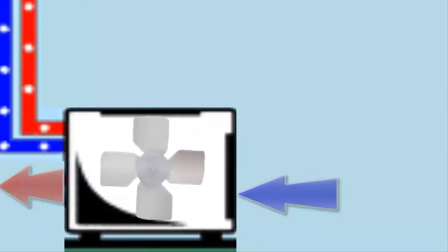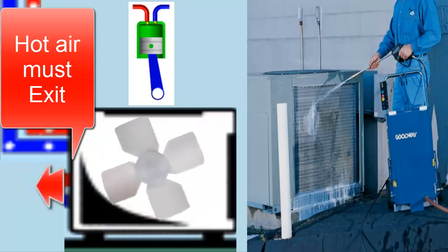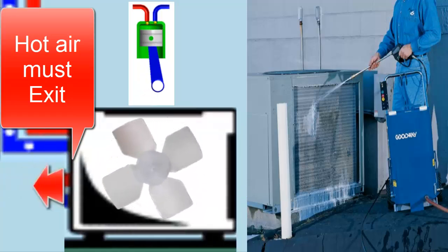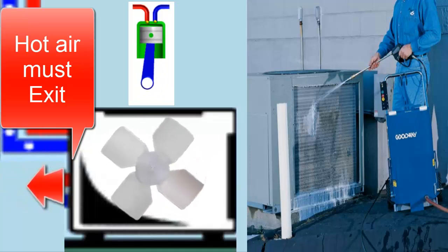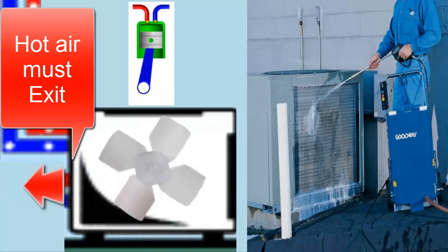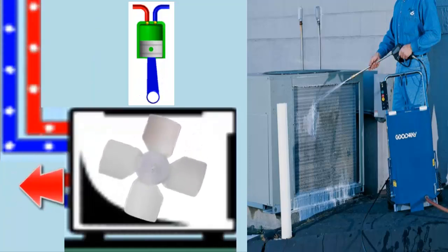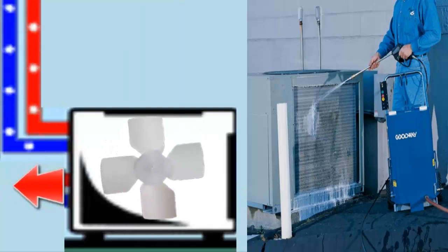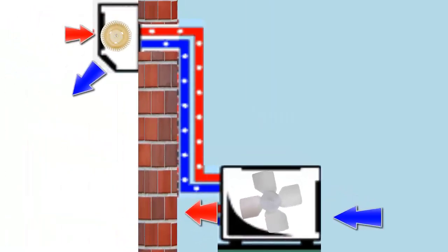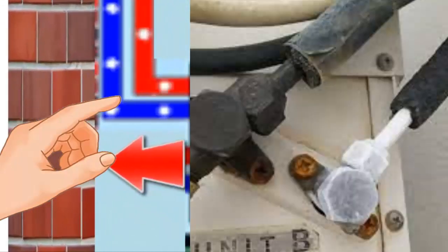4. Outdoor unit. Make sure the outdoor unit is clean and turns on, with the compressor and fan expelling hot air externally, and with the usual noise. A dirty outdoor unit causes the equipment to have low performance. Also, when there is a loss of refrigerant gas, the compressor exerts less effort when working, and emits less noise than usual. 5. Pipe temperature.